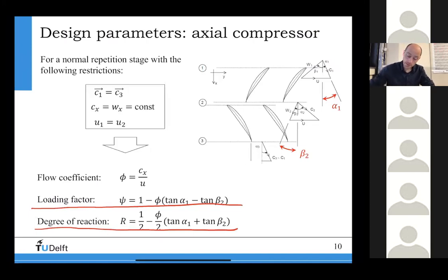And so again, for the compressor, what did we say here? Of course, the inlet velocity, sorry, not the inlet velocity, but the angle of the inlet velocity in absolute frame of reference, which is my C velocity, C1, will be unaffected by the rotational speed. This is U now because we have the rotor here. And it will be unaffected also by the mass flow. So if you have chosen an angle, the mass flow will just increase or decrease the magnitude of that vector, and the rotational speed will not change the angle as well. So the angle that stays constant for a compressor is alpha 1.